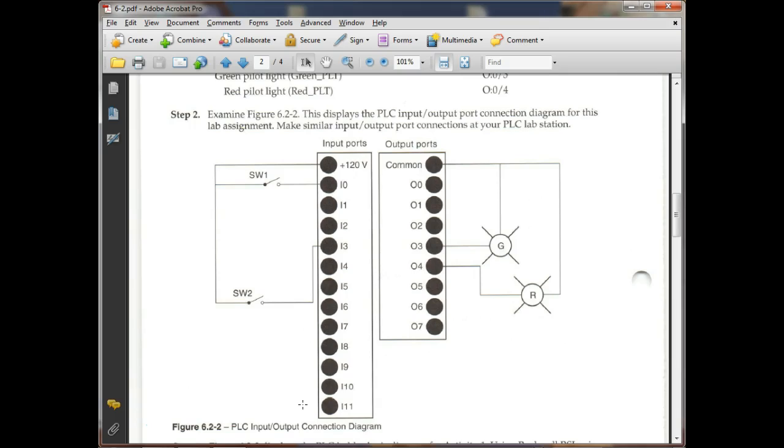Now they've got a little problem here. Can somebody tell me what the problem is? His problem is he's calling this plus 120 volts AC. Now normally out in PLCs, you'll have a common, and it wants you to either use an internal power source, but most of the time now on our input devices we use an external power source. And why?